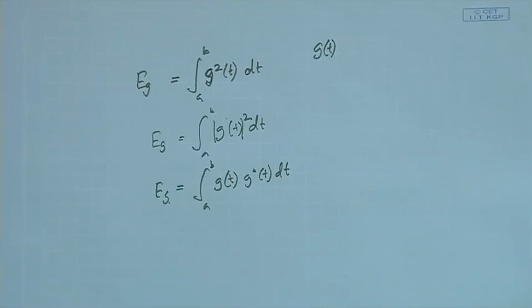This is the measurement of a signal, like we did with the vector analogy. In a vector, it is the distance or the strength of the vector, which is also measured by distance squared. Now, if we want to get the energy value of any signal, it is very easy: take that signal and integrate it over the time that it is defined. Suppose we have that square pulse.